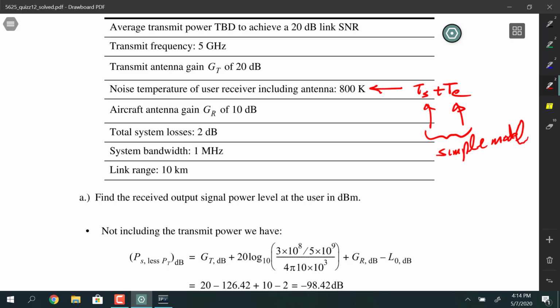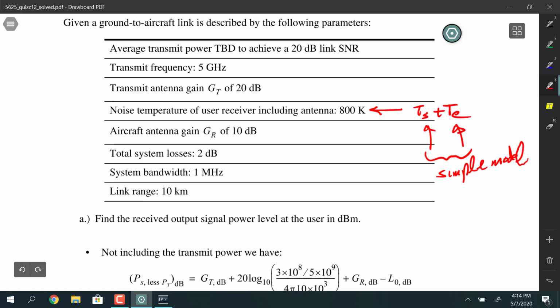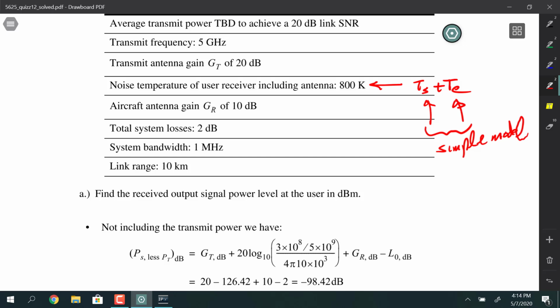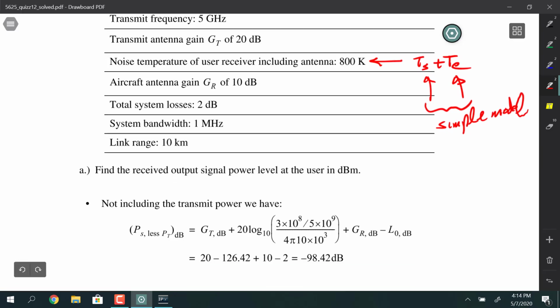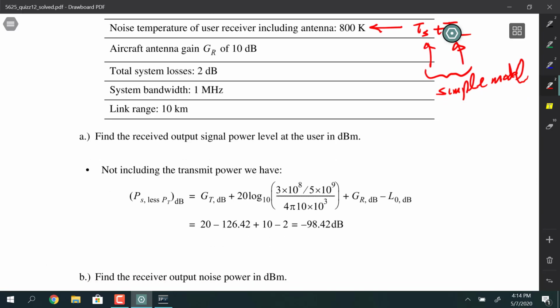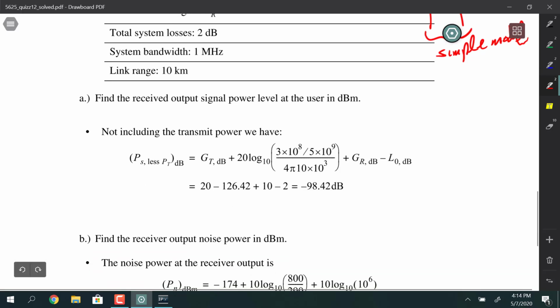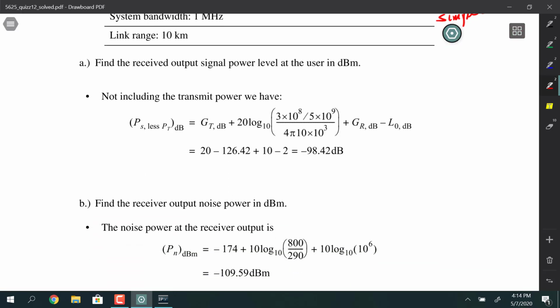And you also know what the gain is of the receive antenna, 10 dB. And, okay, this has got a twist in it. You don't need to know what the gain is of the electronics package. You're going to reference it back to the input to the receiver. So this is going to try to get the 20 dB right at the receiver. I'm trying to see what I'm missing here. Find the receiver output noise power. Find the total noise power at the receiver output.